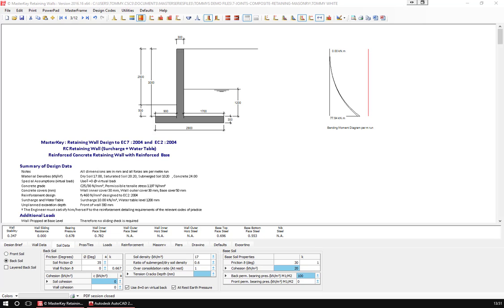Can you apply non-uniform? You can apply non-uniform in that you could apply a series of increasing or decreasing point loads at meter centers, or you could apply a series of 1 or 2 meter lengths of partial loads, but in essence, each load itself is either a point or a uniform load. So we can't do tapering.